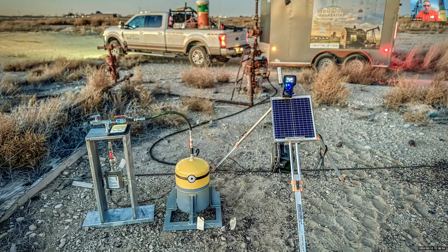And this well was going off, right? Leaking extensive amounts of gas at the surface. We were obviously measuring that pre-plugging to report back to the state and to give the plugging crew a heads up. What we do in addition to the pre-plugging methane assessment is we also then issue kind of a quick little down and dirty safety assessment to the plugging crews about what they're going to maybe see next.